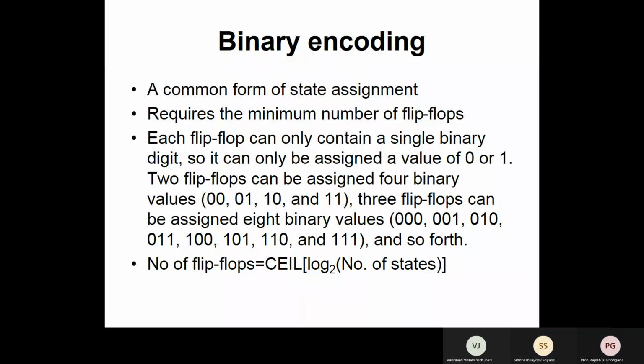Now I can use one flip-flop there because I have only two states. One flip-flop output can be either 0 or 1, so the two states can be distinctly represented. Are you able to understand this? Yes, sir. So I can use only a single flip-flop there.